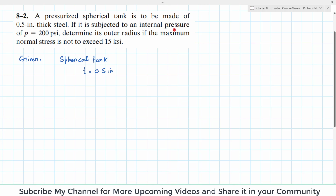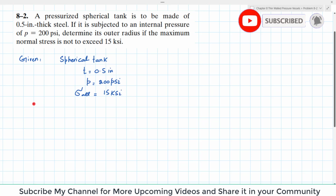Clear? If it is subjected to internal pressure of 200 psi, pound per square inch, determine its outer radius if normal stress does not exceed 15 ksi. So allowable or maximum stress is equal to 15 ksi. So what we have to find is its outer radius, which is R outer. Clear? So let's start with the solution.